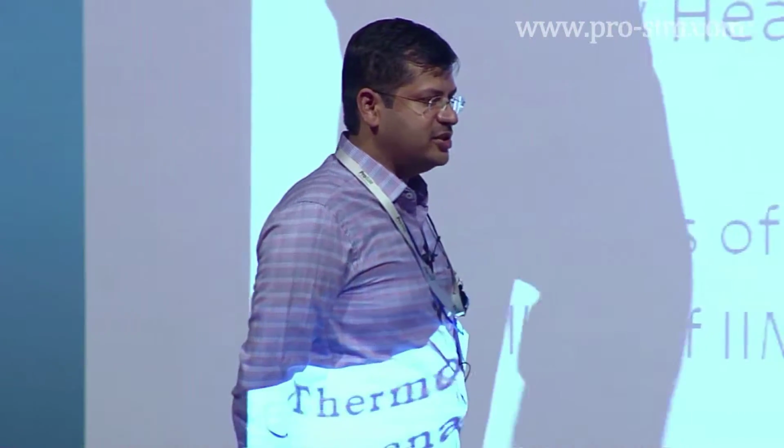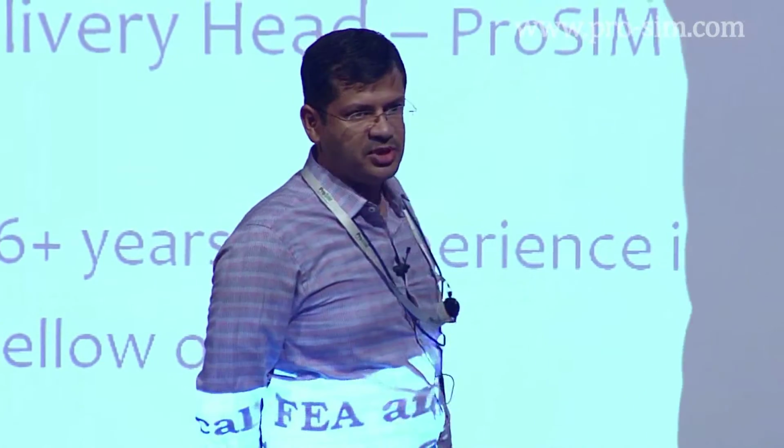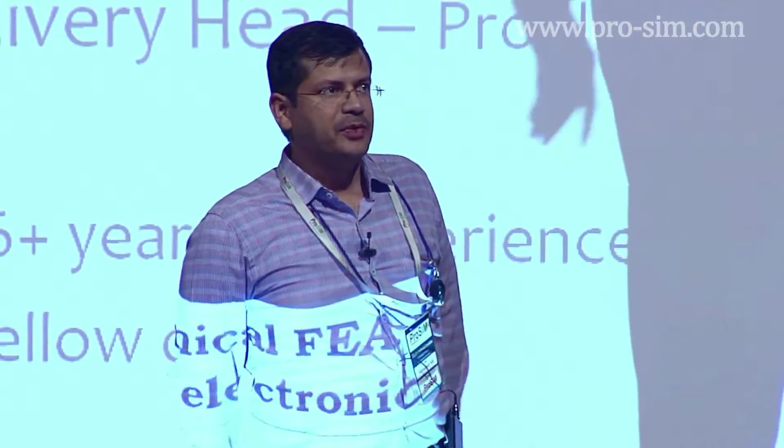Material, there were different material structures like PCB structures. We did not get enough details from literature. I think the damping value which you used is a bit less. 2% structural damping. Yes. I think that's small. Predominantly, yes. In steel structures, we use 2%, 3% structural damping. It's some kind of plastic, right? No, the chassis material is aluminum base, and we had relatively very few non-aluminum PCB structures. So overall, the structure was predominantly aluminum.